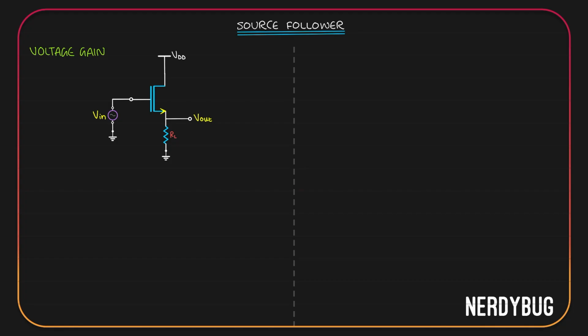As always, the first thing we need is the small signal model. It's going to be very simple. All we need is the small signal model of a MOSFET. At the source, we'll have RL. Drain is directly connected to VDD, so drain will be at the AC ground. It'll look like this. How about we also include channel length modulation? In that case, there will be a resistance R0 between the drain and the source.